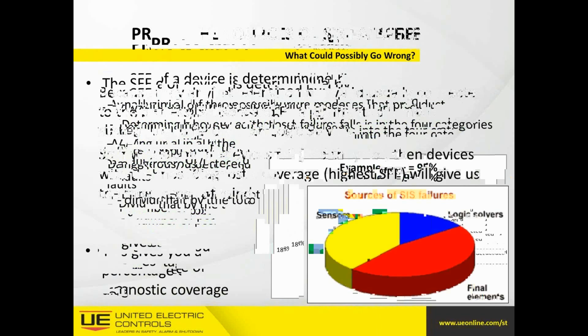The sensor is also very critical, but sensors can, in some cases, deliver very, very high or significant safe failure fractions. So in some cases, they could buy us some points on final elements that have poor performance as a safe failure fraction. But for my study today, we're going to stay focused on the sensor and what high safe failure fractions with a sensor can deliver in a total safety instrumented system.